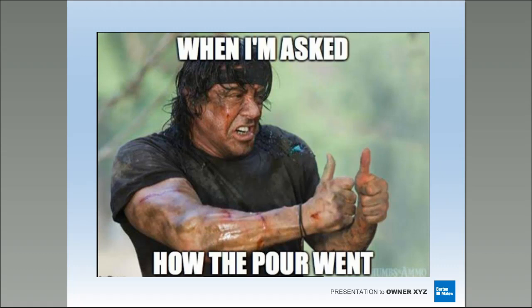So yes, there are ways to mitigate the exposure of the fiber on the surface, and you're going to want to take care of it on the placement end. On the polish end, you really don't have any way of limiting the exposure because the canvas has already been served up to you. So when you're talking about a steel fiber floor, you really want to have a good long sit down with your place and finish guy. Make sure they're using that roller bug.